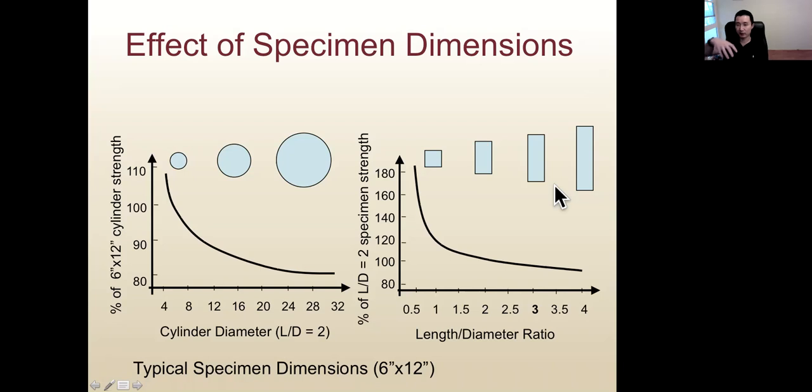That is because, remember, on the top and bottom the steel plate provides a constraint effect, preventing the concrete from cracking under tension stress in the horizontal direction. If we increase the L to D ratio, the constraint effect is lower, so the concrete will crack earlier.